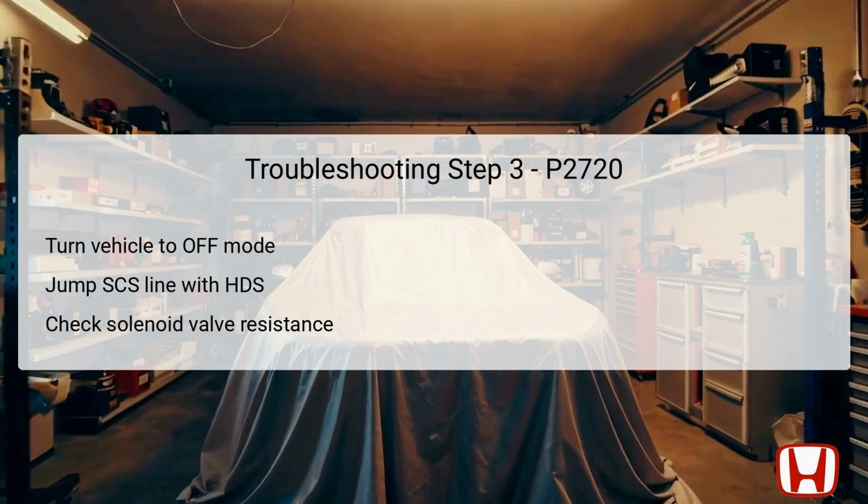With the vehicle still in off mode, measure the resistance between test points specified, using number 3 of PCM connector C and the body ground. Ideally, the resistance should read between 5.0 and 6.3 ohms, which would indicate that the control solenoid valve is operational.